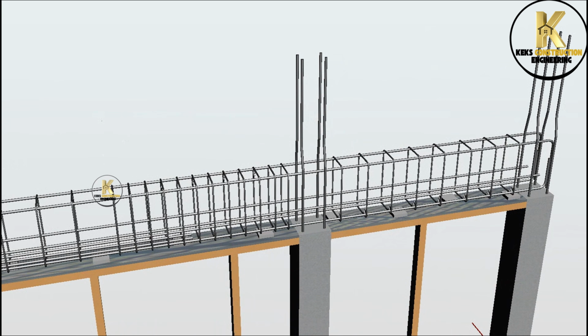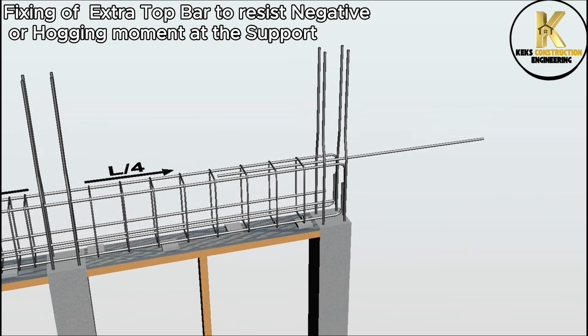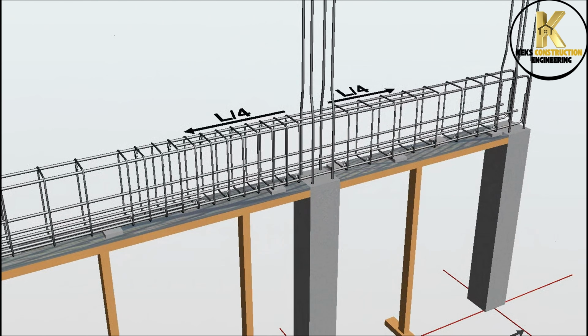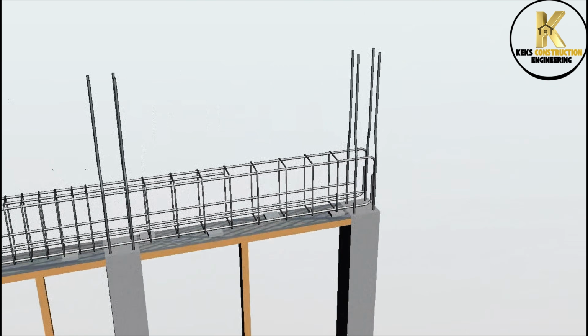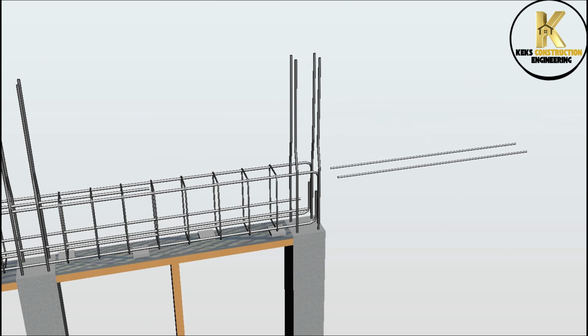Using the L/4 rule for curtailment to determine the length of extra top bar. Fixing of extra top bar to resist negative or hogging moment at the support. Fixing of the second layer top bar T2 to resist negative or hogging moment at the support.